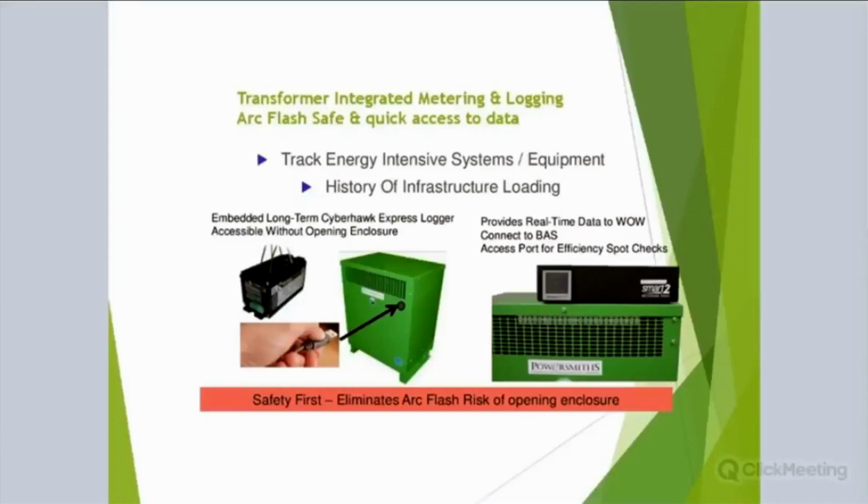Or you could log. The picture on the left is of a data logger that sits in the transformer. You access it through a USB port in the front, and you can download what is the loading on that transformer, what's its efficiency, and see that log report so you can determine if you're adding load later to that transformer, you already know what your existing load is, as opposed to having to test it for 30 days to get that load.